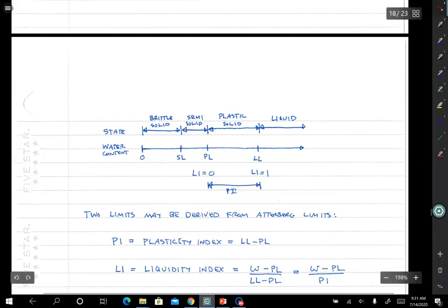All right, another important index is the plasticity index. We've defined liquid and plastic limit. Well, it turns out that a really fundamental parameter that's closely related to the types of clay minerals in a soil is the difference between the liquid and plastic limit. If you have really flat, thin clay minerals, the liquid limit is going to be very high, and the plastic limit will be a little bit higher than other clays, but the difference between those two will be very big. If you have a clay that is not so thin, a little bulkier, to where the mass of the particles has more of an impact than those surface charges, then the difference between liquid and plastic limit will be smaller.